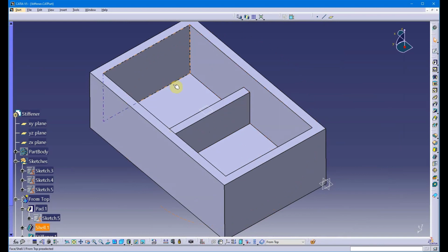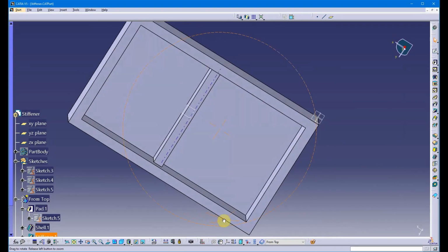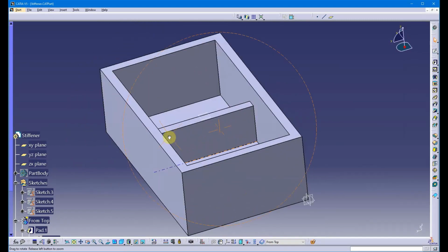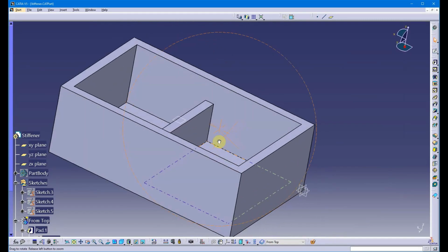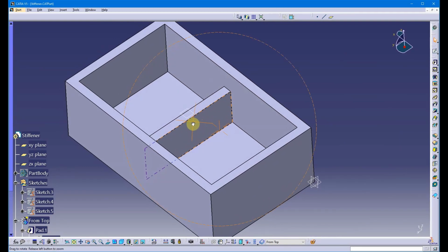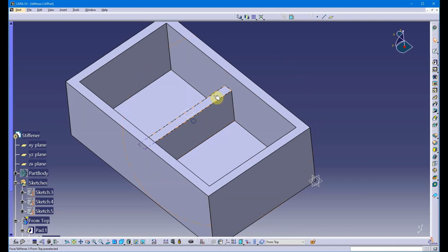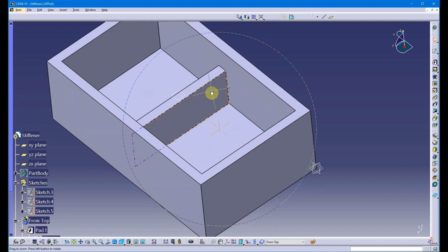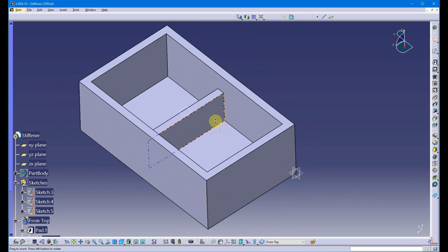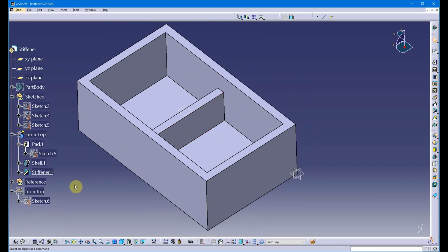So just imagine that this is a plastic part, or very simple plastic part, probably couldn't be molded very easily, but that's not the intent of the demonstration. But you can thin the walls out and provide stiffeners in that will help you to make this a little easier to manage. So let me show you another example here. So I want to take this out. So let's say I didn't have any stiffeners.